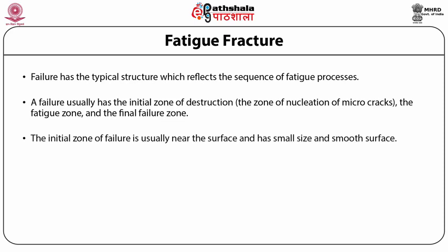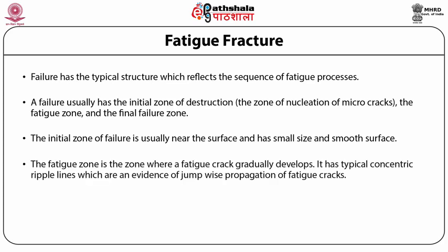The initial zone of failure is usually near the surface and has small size and smooth surface. The fatigue zone is the zone where a fatigue crack gradually develops.